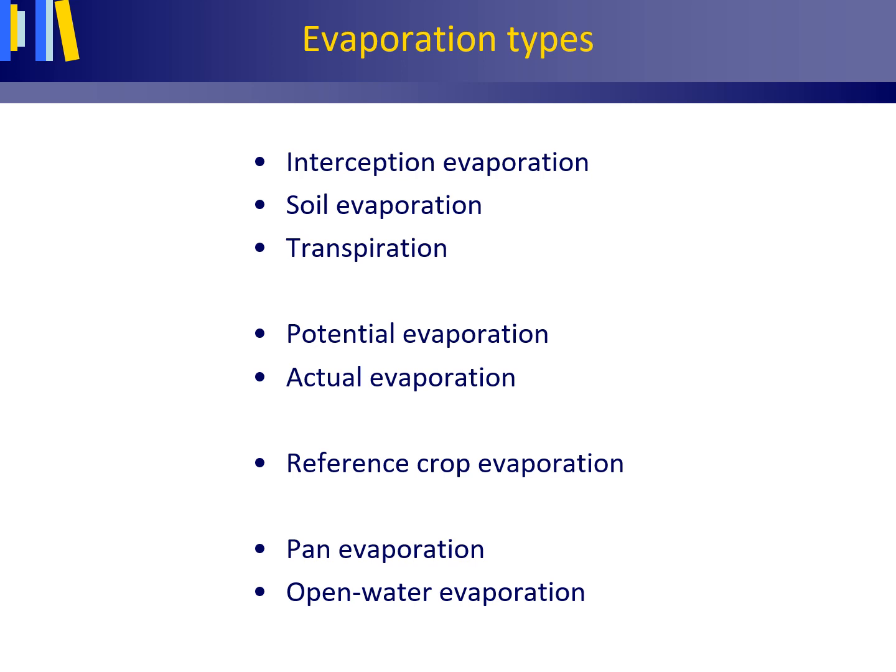A low-budget and direct way to obtain some measure of the evaporation rate on days with no precipitation is to use a pan filled with water and to measure the height of the water in the pan for 2 consecutive days at exactly the same time. The difference in height in millimeter divided by the time interval in day yields the pan evaporation in millimeter per day.